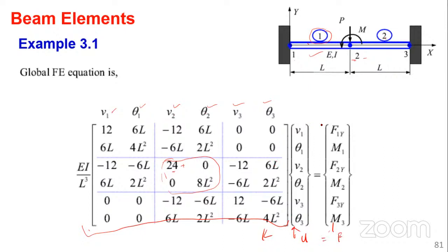So with this now, you go ahead and solve this equation. To do that, we need to reduce it. Otherwise, the way it is, we have so many unknowns. We do that by invoking the boundary value problem, which means we are fully defining our problem. As I said from lecture number 1, in the finite element method we are solving a boundary value problem. So without defining the boundary conditions, we have not fully defined our BVP.